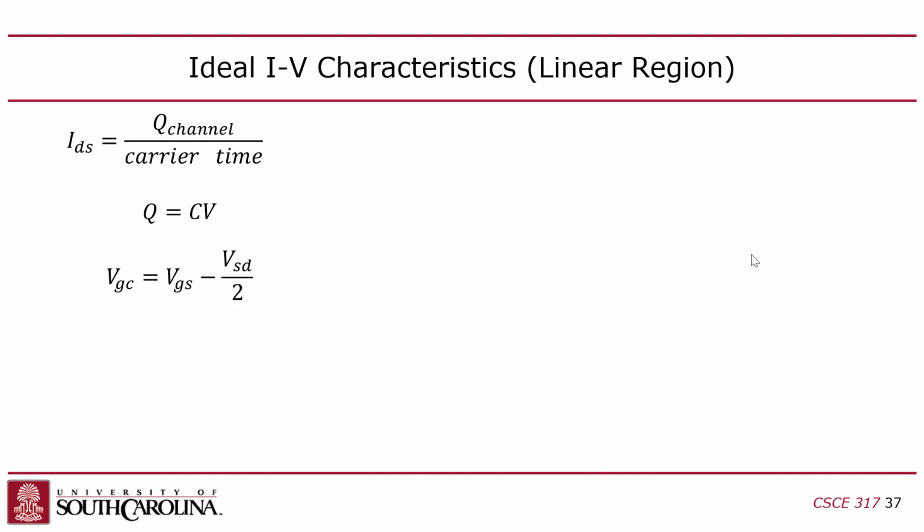And the voltage is the gate channel voltage, which, as I mentioned earlier, it's a little tricky to figure out, but it's essentially the gate channel has to be calculated as a function of the gate and the source drain, right? Or you could do it as gate source, gate drain, or you can restructure it like this, gate source, source drain, right? Why? Because again, that fourth terminal, which is the bulk, the body of the transistor, the substrate, does not factor into this. The gate channel is only a function of these guys. Okay, so that's what you use for voltage, and then of course the capacitance is whatever the capacitance is.